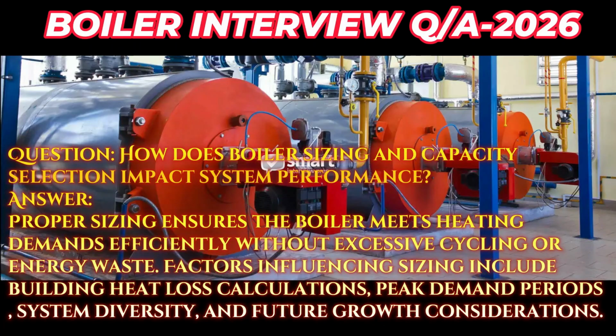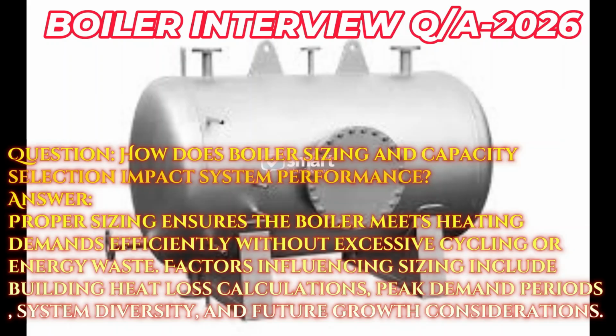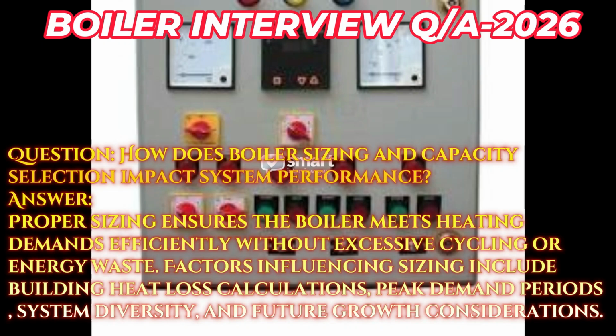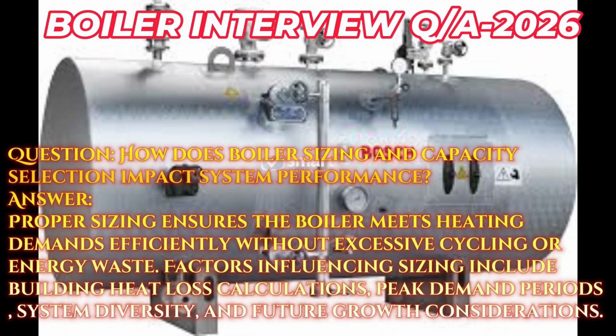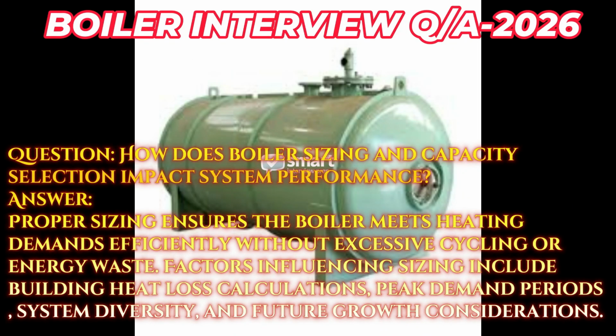Question: How does boiler sizing and capacity selection impact system performance? Answer: Proper sizing ensures the boiler meets heating demands efficiently without excessive cycling or energy waste. Factors influencing sizing include building heat loss calculations, peak demand periods, system diversity, and future growth considerations.